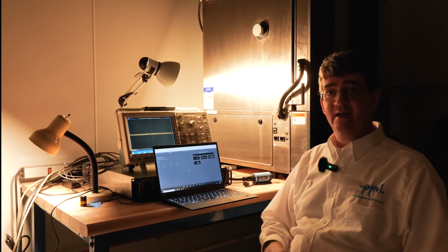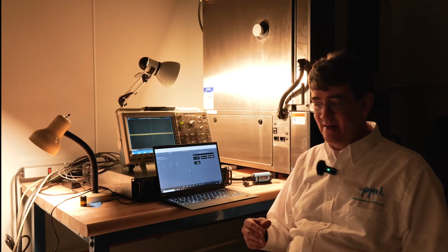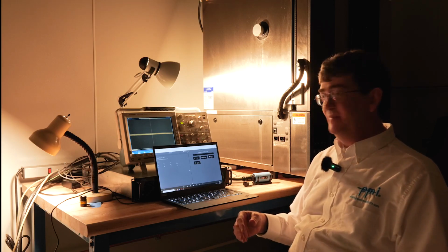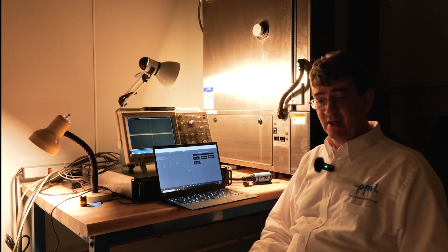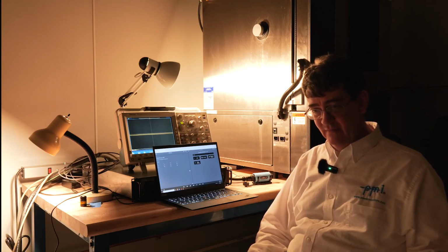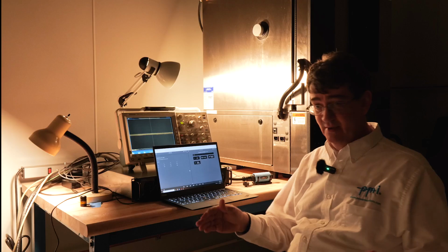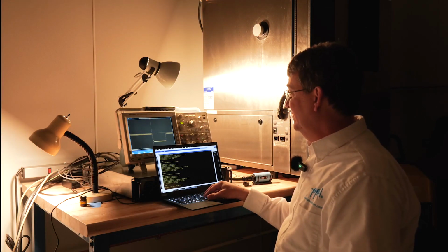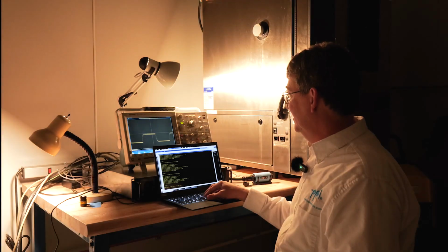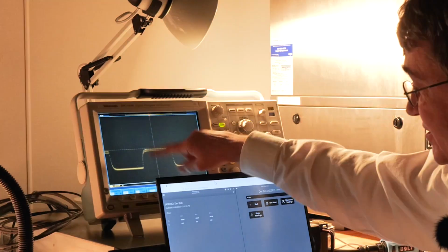And now we're going to check the other end of the scale to make sure we have a wide dynamic range. We're going to go to a PST of 20, which is an extreme level of flicker, to make sure the Bolt has enough dynamic range to cover the very low levels that you might see and very, very high levels. So let's set the source for that. Now we have a very visible amount of flicker. You can very easily see it in the lights. You can very easily see it on the scope.